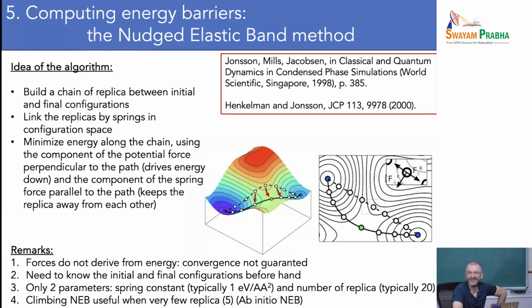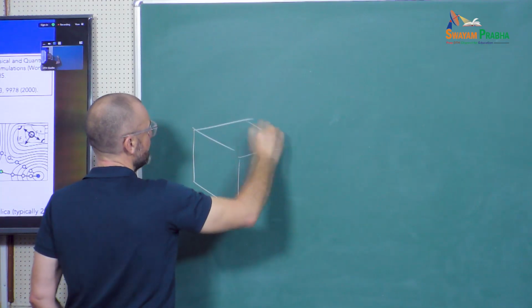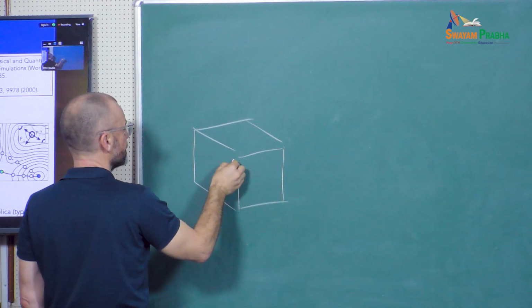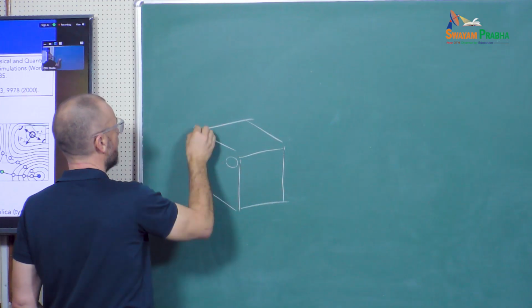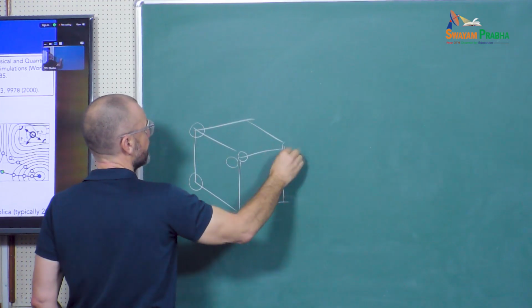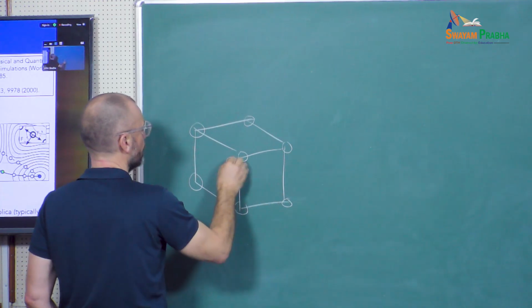No? So actually I made a mistake because the vacancy jumps directly to the second neighbor and not to the first neighbor. So you have the energy that you get, which is actually very high, 2.1 eV. It's much bigger than what it should be. I should have realized, but in the rush when I did the calculations, in BCC, so this is for iron, right? So it's BCC, so I have an atom in the middle, and then I have atoms on the corner.